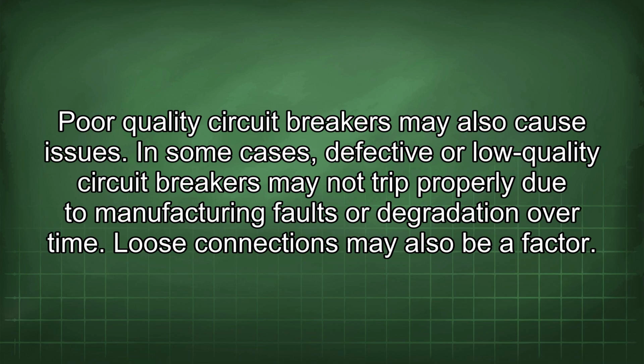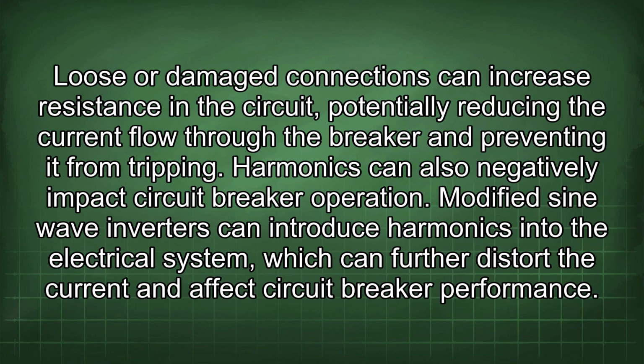Loose connections may also be a factor. Loose or damaged connections can increase resistance in the circuit, potentially reducing the current flow through the breaker and preventing it from tripping. Harmonics can also negatively impact circuit breaker operation.